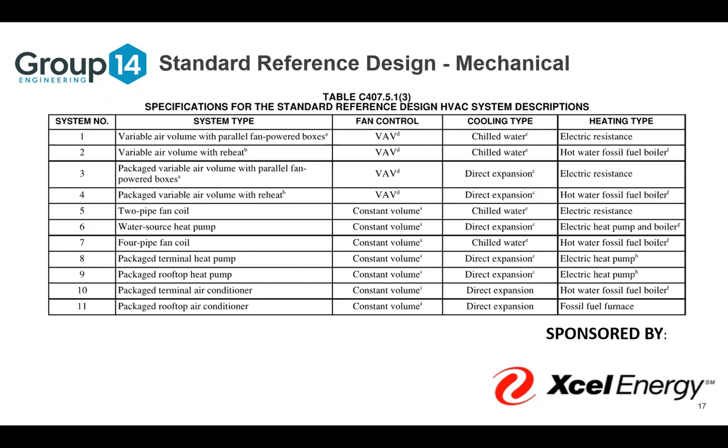So a water source heat pump in the baseline to a water source heat pump in the proposed. Something to keep in mind there: double check and make sure that they are selecting the correct HVAC system within the baseline model. There are all these notes below this table that tell you exactly how to model each system, and it's almost a full page of